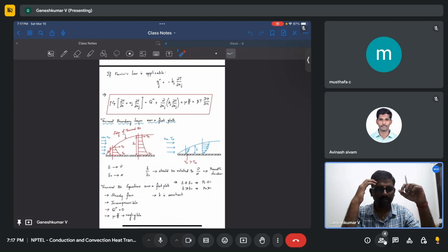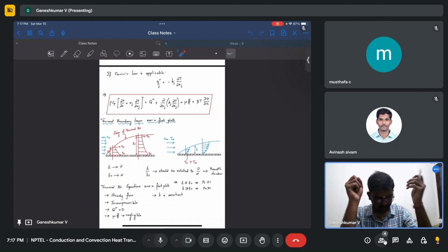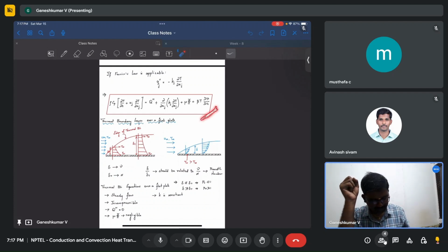If you think back, we started with Reynolds transport, and we derived the mass and momentum equations, and we found out that there's an additional pressure. So there are 3 velocities, density, and the additional pressure: 5 unknowns, but you have only 4 equations, 3 momentum and 1 mass conservation. So you need one more equation, and you added the equation of state. And what did the equation of state do? It added temperature also to it. So you need an additional energy equation, and this is what the energy equation is.